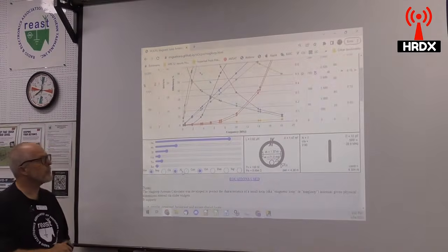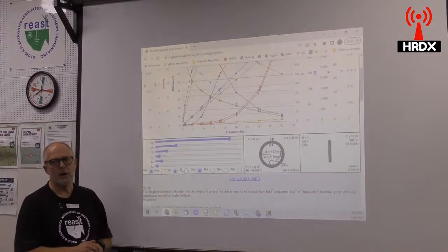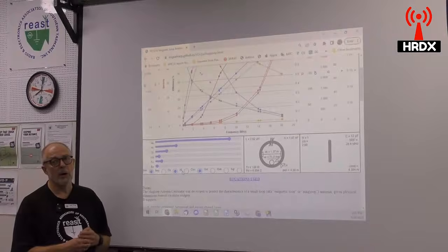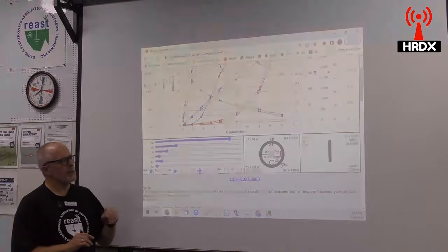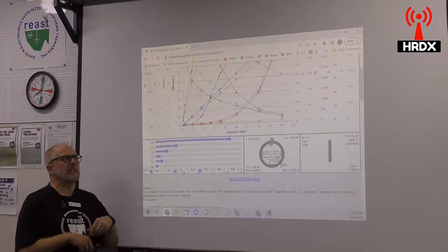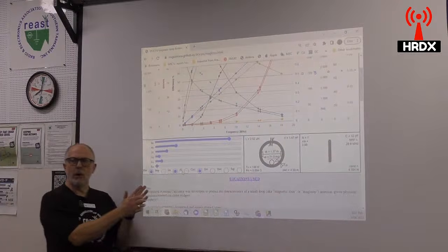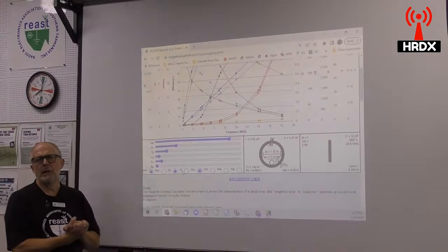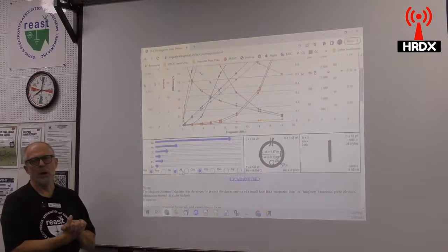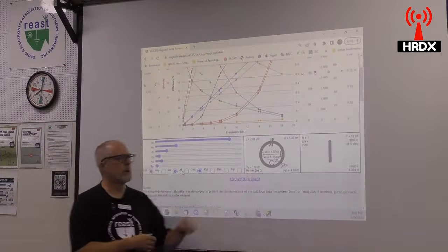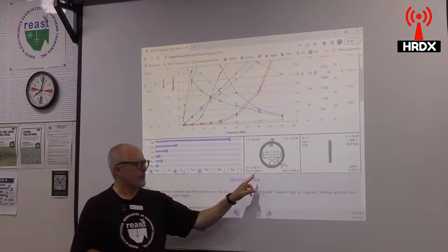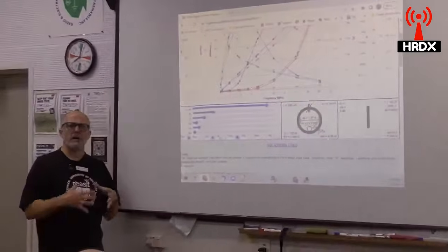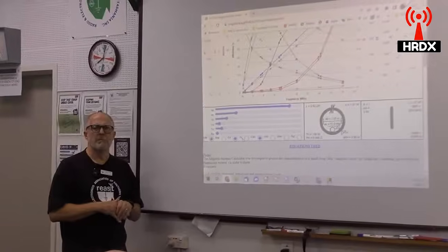But Justin, in terms of you measuring the DC resistance of the coil, is that valid when you're dealing with the radiation from the surface? Interesting point. I assume it is, because they actually take into account the expected radiation resistance from having this ohmic resistance in the calculation. It'd be quite different if you could make a solid piece of copper, the DC resistance would be much less. I made a point a bit earlier: with magnetic loops, where you get it down to this sort of level, the radiation resistance is so low anyway, I don't think it would change that much. But interesting point.